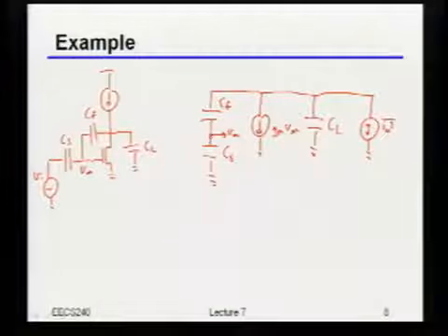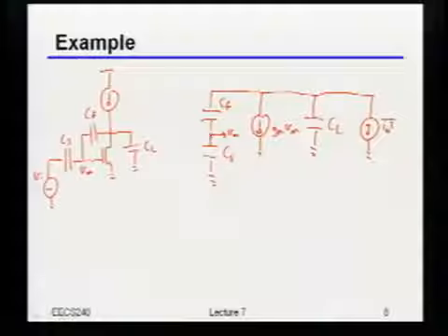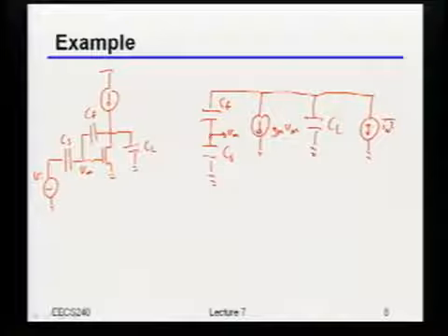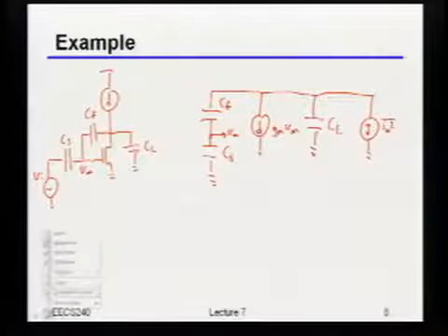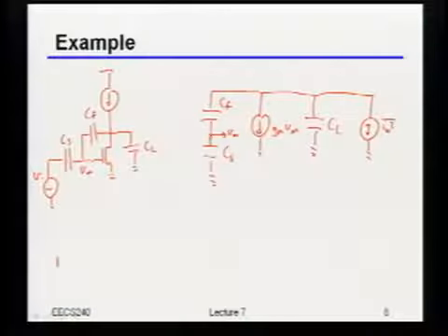Procedurally, obviously, I could go and just write some KCL and KVL equations and do some integrals and figure everything out. I claim this is going to turn out to be a really easy problem if we just look at things the right way. So to do that, I want to ask the following question. If I look at this network here at DC, what's going to be the resistance that I see looking from the standpoint of the noise current over here?